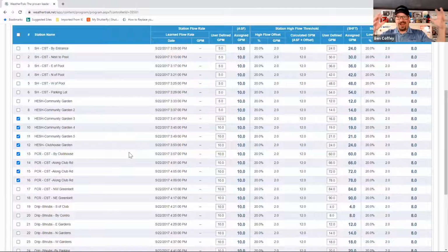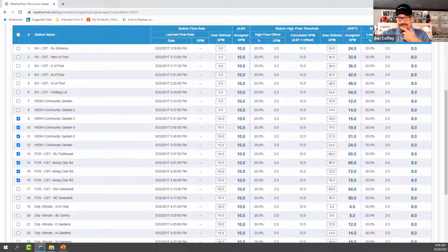And so again, I've got this place where I can either run one of each, or I could be running as much as 5 of the small stations, right? That allows that OptiFlow to really do its job and to capture some of that time savings. It's just math. That's the easy step to take, right? That we're not using the actual flow information. OptiFlow is just doing the math in the cloud and deciding what can run. And it's not a lot of math either. You're just really looking at those 2 values. What's the station flow rate, and then what's my mainline flow rate. So it's really simple. Exactly right.